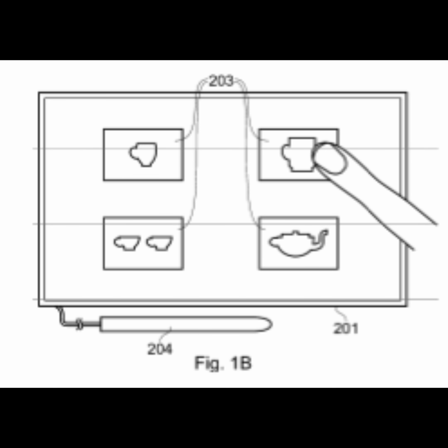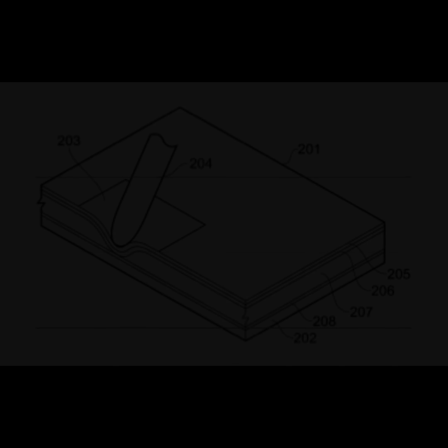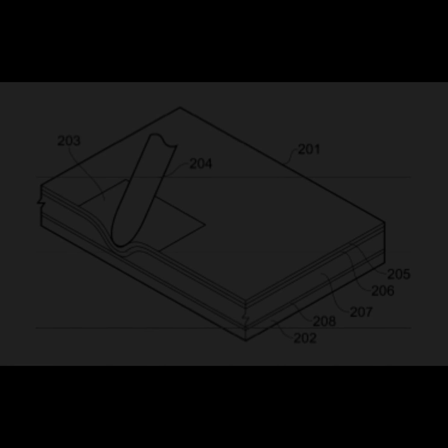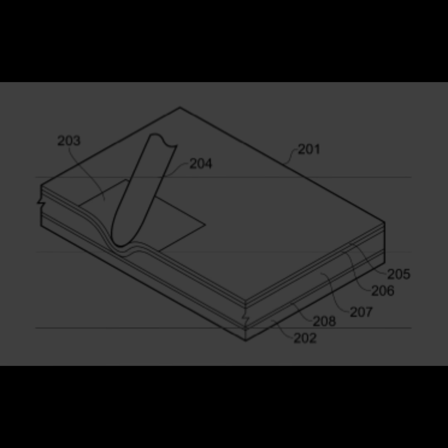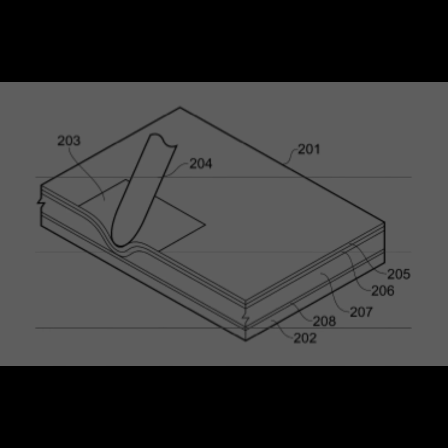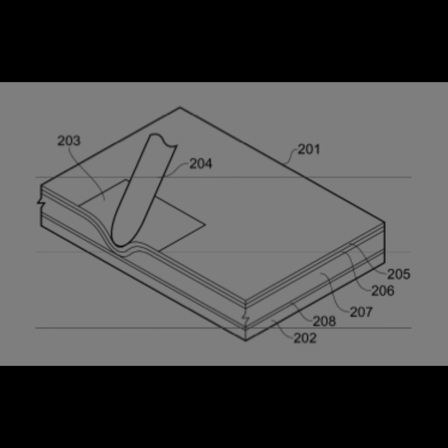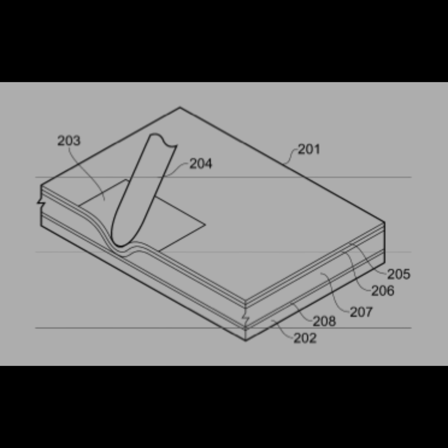The interior surface of the hemispherical support, 112, is provided with a resistive layer 116. The resistive layer is a continuous band in the form of a spiral. A narrow separating region, 120, of the support, 112, electrically isolates adjacent turns of the band. The resistive layer, 116, is connected to a voltage supply in a control unit, 119, via a pair of contacts, A and B, located at the ends of the band. The control unit 119 is mounted on the cover 113.